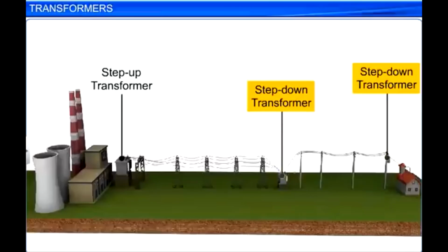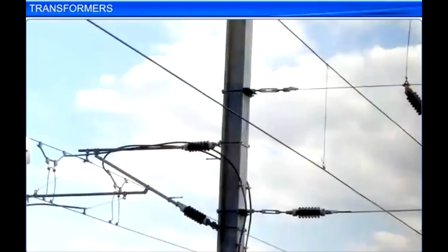There is a practical upper limit to the voltages we can use for transmitting the electrical energy through the transmission lines. Excessive voltages can ionize the air around the transmission lines. This in turn can create a conducting path to the ground or other objects near it, and also can possibly cause damage to life and property in its vicinity. Hence, long strings of insulators are used to keep the transmission lines away from the towers supporting them, and insulators are also used to maintain separation between the wires.